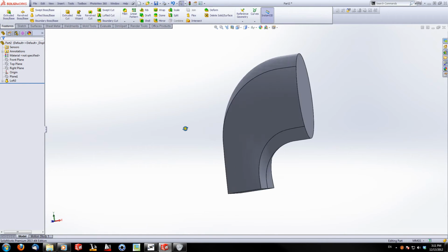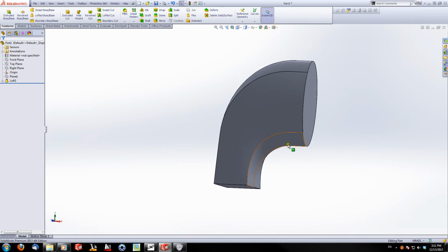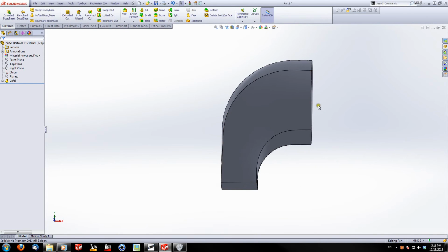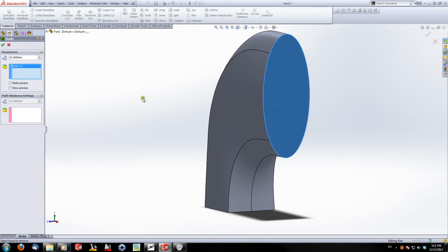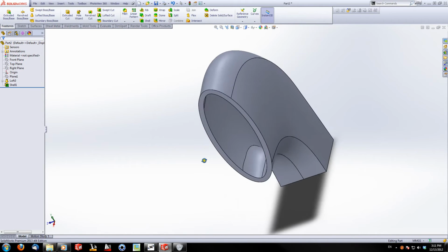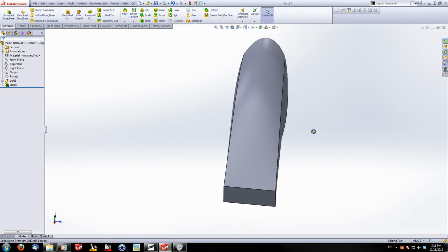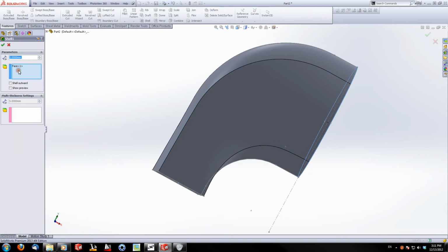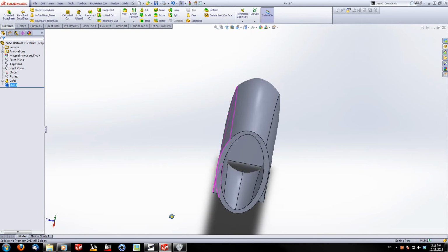And there it is. So you can see we went from a straight shot into a guided geometry, which better translates the 90-degree, the perpendicularity of our 2 sketches. And then just like before, if we wanted to, we could even shell this, and it will generate a hollowed out feature. And you could even shell this from both directions too. So if you wanted to shell it from here and here, it would create like a pipe or a tube.